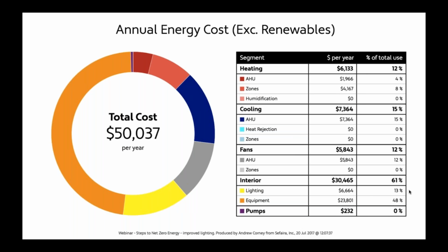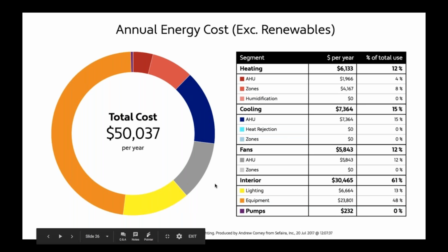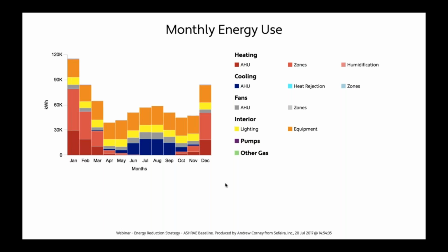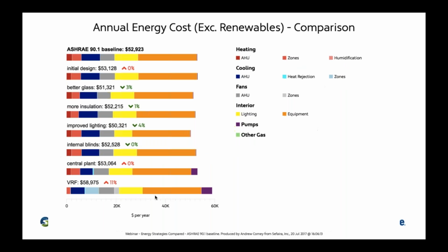We used a reduction strategy to reduce that lighting, perhaps some LED lighting in parts of the building. That reduced it in the first instance. Then we looked at cooling, which was the next highest element. Perhaps we looked at monthly energy use to see where and when in the building energy was being used. Perhaps it showed us that we needed to apply more insulation for winter heating.